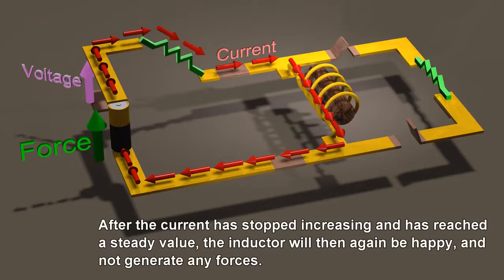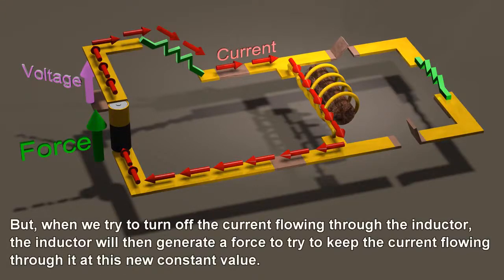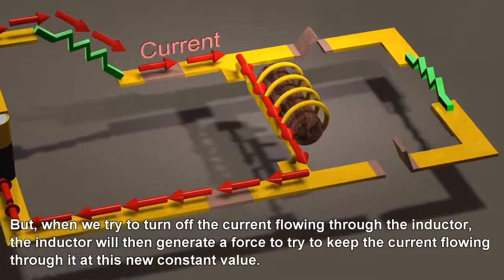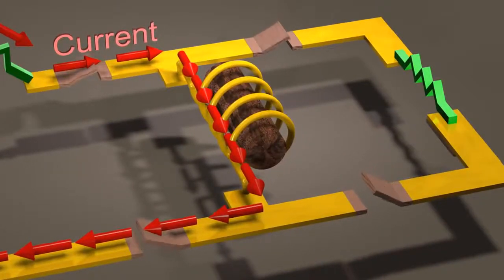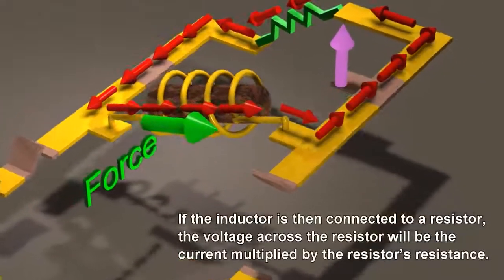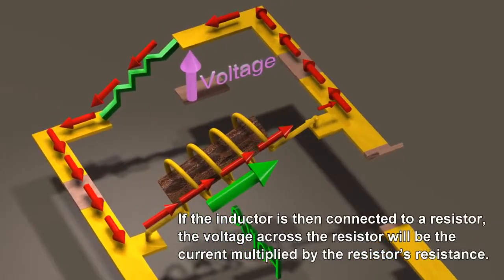After the current has stopped increasing and has reached a steady value, the inductor will then again be happy and not generate any forces. But when we try to turn off the current, the inductor will then generate a force to try to keep the current flowing through it at this new constant value. If the inductor is then connected to a resistor, the voltage across the resistor will be the current multiplied by the resistor's resistance.